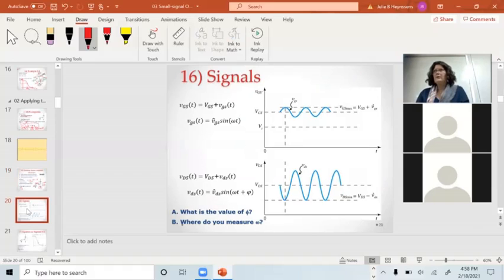If I actually go and plot the input signal and the output signal, you can see it has two parts to it, and you get to do this on one of the homeworks. My little v, big G, big S, my total signal, is a DC part, steady state, plus some AC signal riding on top of it. Literally the sum of those two voltages.